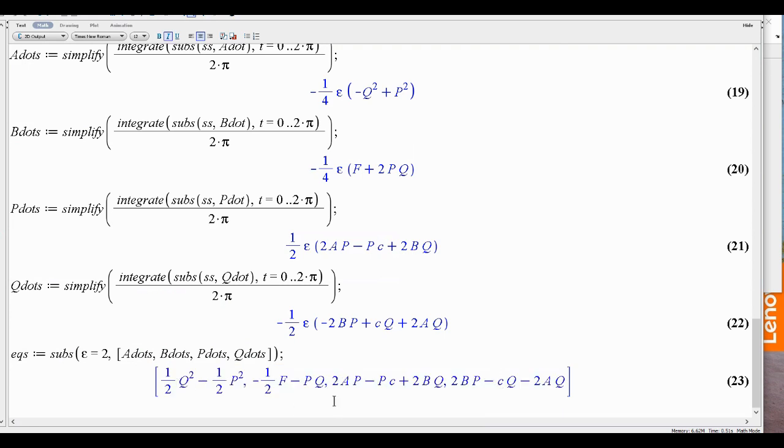You will find stability results, which from the original are much harder to find. So the averaged equation is partly interesting academically, I think it's pretty. Partly it gives you insight in some cases. It lets you obtain equations that you can, even if you numerically integrate them, proceed much faster. And this example in particular was intended to be a demonstration of averaging for a 2 degree of freedom system. Thank you.